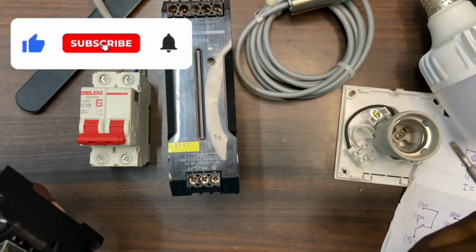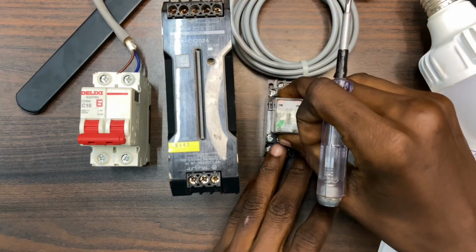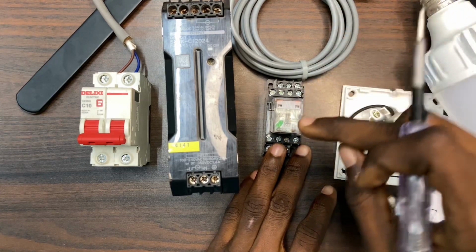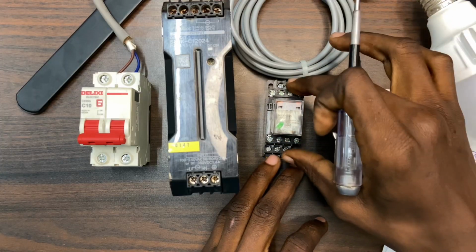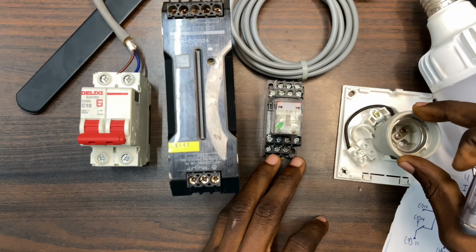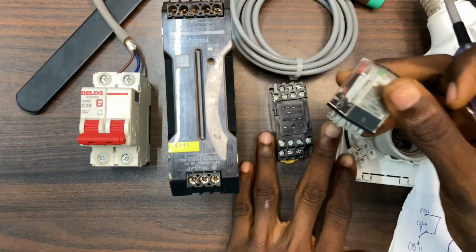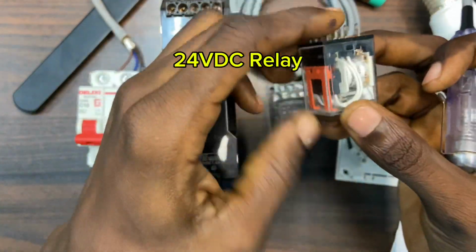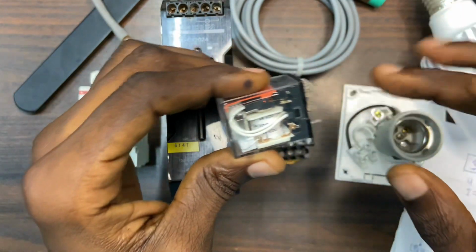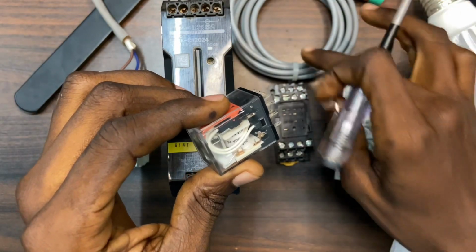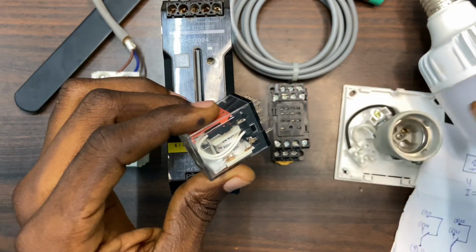And in order for us to control the load using this DC proximity sensor, we have to then use a relay. We are going to connect the proximity sensor to this relay you see here. This is a magnetic relay, and we are going to use the relay, the normally open and the normally closed, to control the load. The sensor is going to help us energize the relay. This is 24 volt DC relay, and that is what we are going to use to control the load. The sensor is going to energize the relay, and the relay is going to open the way for the current to flow to the load.